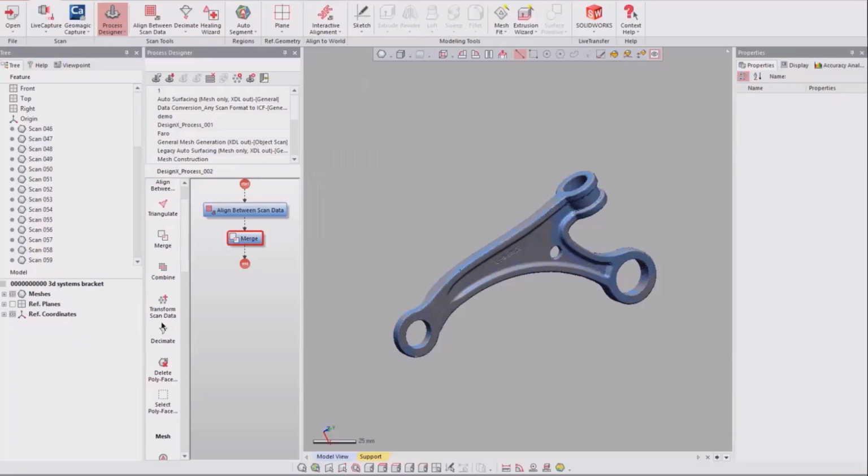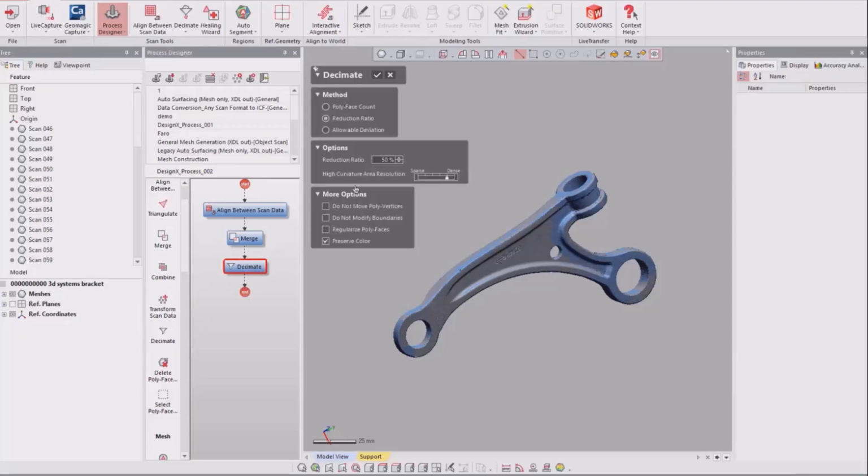Now, after that, what I like to do is go ahead and decimate the data set down to a known size. When I scan this object, it could be 30 million points. I'm not sure exactly how many points or triangles that is, and it's going to merge everything. Then I like to reduce it down to a specific size.